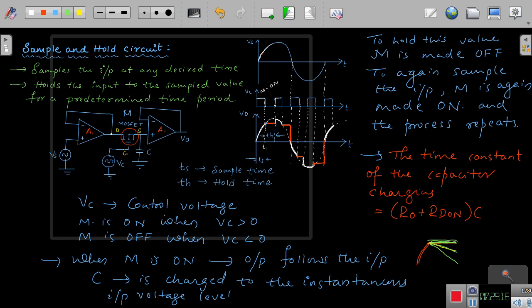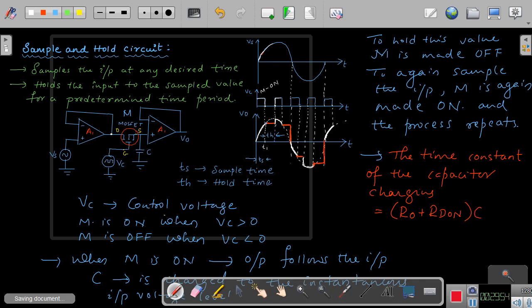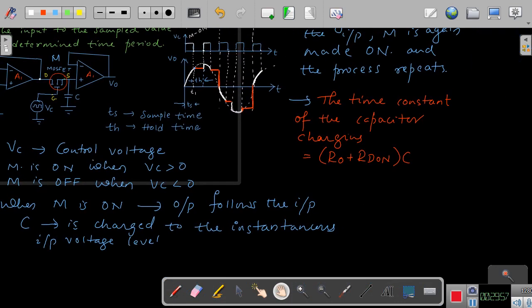So ideally speaking, we want to have the holding time. During the holding time, the capacitor deployed holds the charges firmly, like that. Here we cannot use the ordinary capacitors for the purpose of sampling and holding, especially when you require the sampling to be very precise. So there are different capacitors deployed which have very low leakage factors, or very good dielectric constant or something like that, right?